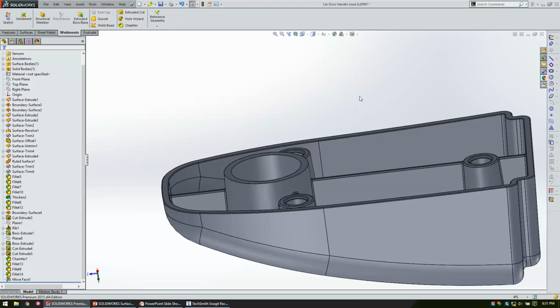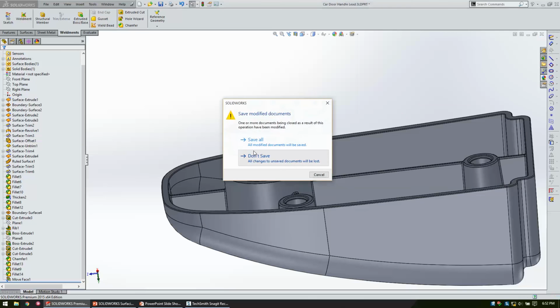We're like, okay. So you go into our model, and there's so much built on top of it that when we went to the original sketch and just moved it 4 inches, everything blew up, which happens in surfacing. That's just a reality. So we just took the cheater way out, and we just said, pick all of those faces. I think we just right-clicked and said select tangency, and then Triad moved it 6 inches, and in one feature it was done. So the move face command is extremely powerful. I should probably come up with a better example and add to my presentation, but I encourage you to leverage that if you ever run into that situation.